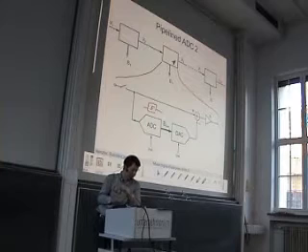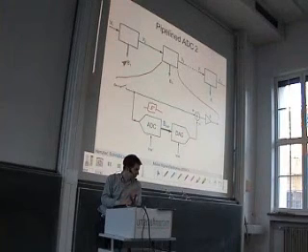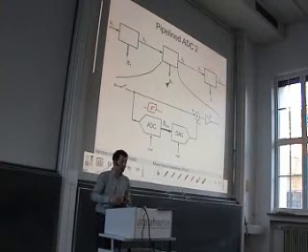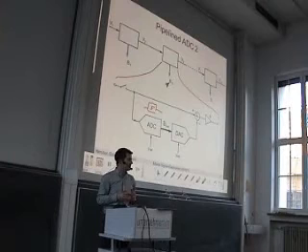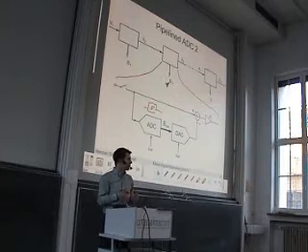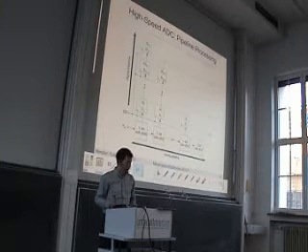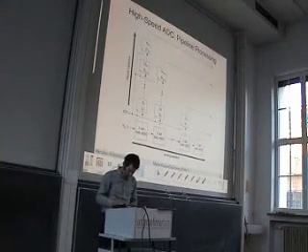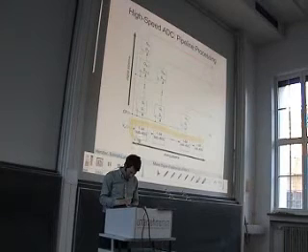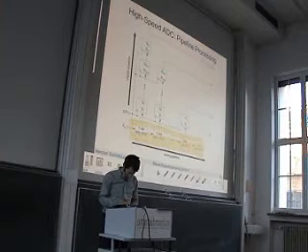So at the end, we get something like this. We get here the first bit of one sample. Here we get the second bit of the previous sample, and so on. So at the end, we have to resort the bits, so that all bits belonging to one word are actually delivered in one word. And this can be done by a so-called queuing circuit in the digital domain. So here you can see that we have our pipeline. This is pipelined in an analog fashion.